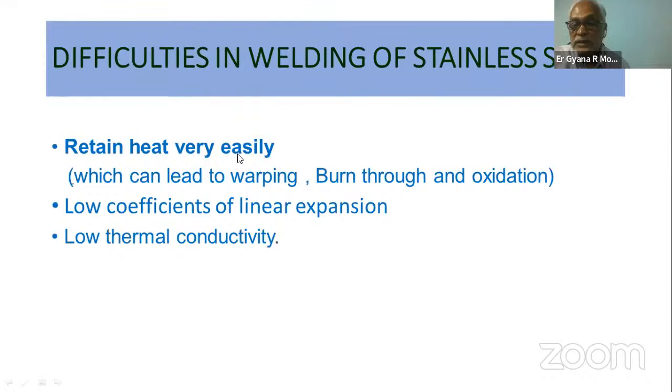When using thinner stainless steel, you would never use it with DC electrode positive. Mostly, thinner stainless steel is welded with TIG welding. TIG welding is not used in bridges. So because of this warping tendency, stainless steel in critical operations is mostly done with TIG welding, where the electrode is made negative and the maximum energy is generated in the electrode and not in the job.